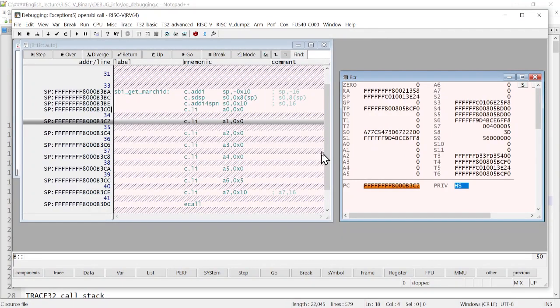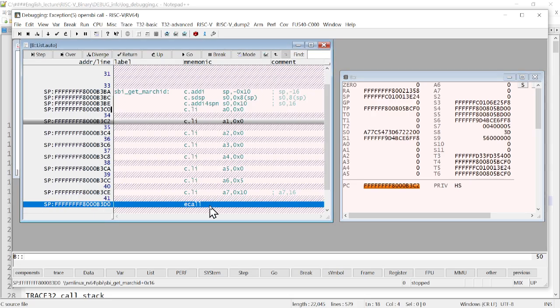Now let's continue another interesting debugging in practice. The screen you are looking at is the software assembly instruction in the supervisor mode. In the supervisor mode, as you know, the Linux kernel runs. So in this debugging practice, I'm going to run the ECALL assembly instruction in the supervisor mode, and you're going to see what's going to happen from the RISC-V perspective.